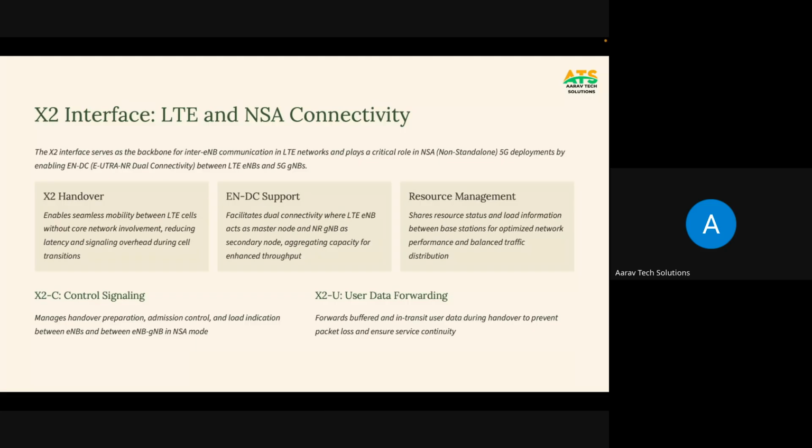In LTE also, you might have heard about the X2 interface, for the X2 handover, S1 and X2 handover. This is for EN-DC dual connectivity, as I told, and this is used for resource status and load sharing. For the load sharing, the X2 interface is being used. Further, like other interfaces, this interface is also split into control plane and user plane, X2-C and X2-U, where X2-C is for handling the control signaling operations and X2-U is used for user data forwarding during the handovers. So this is for the X2 interface.